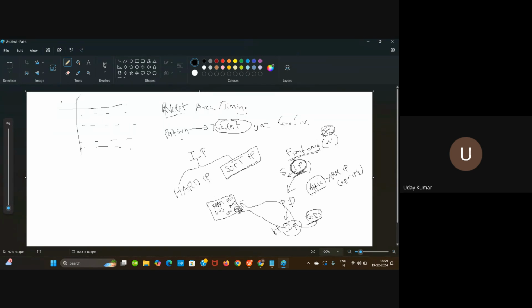And when he is doing physical design, he will involve this GDS. So he will not be able to change or customize anything logically. Once you harden some IP, once something becomes a hard IP, you cannot alter any logic there. You will be just able to use the hardware. That's it. I hope things are getting clearly understood.